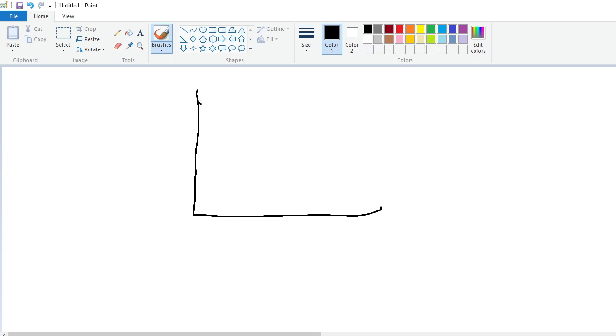So this is the actual load line, the line drawn between the saturation point and cutoff point. Now instead of RC, a coil is connected. So what happened? The slope of that load line becomes infinite. That means it becomes a straight line. So what is the load line? It is the line drawn between the saturation and cutoff point. So this point becomes VCC. Why? Because it is operating in the active region.